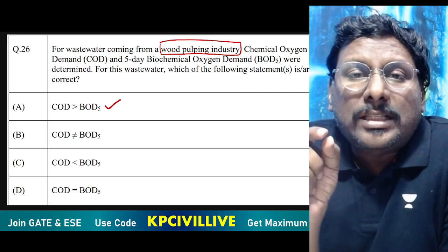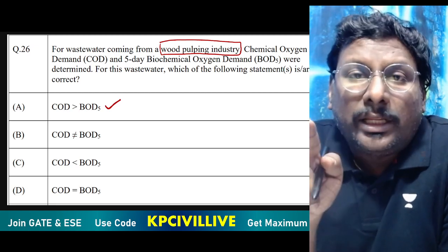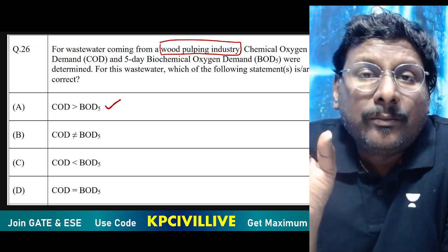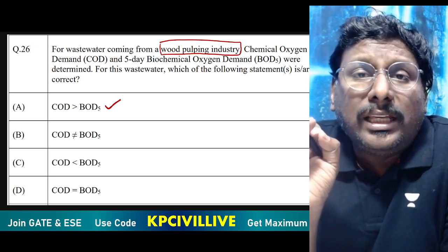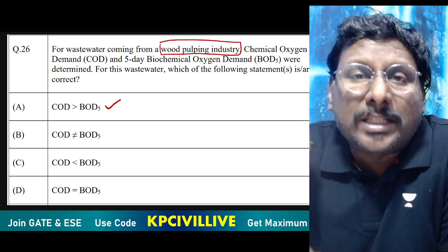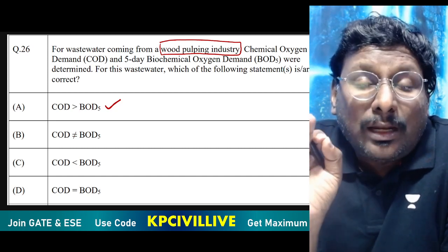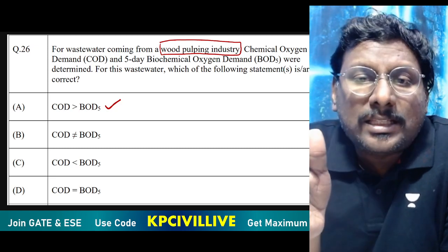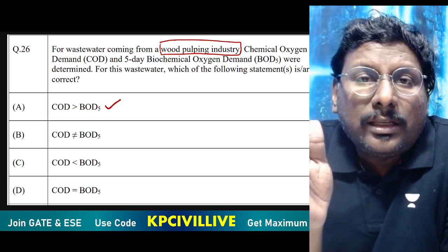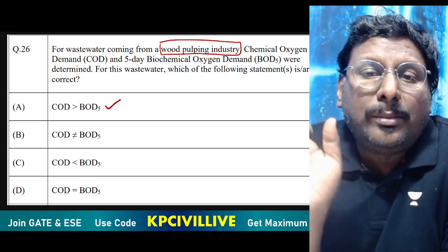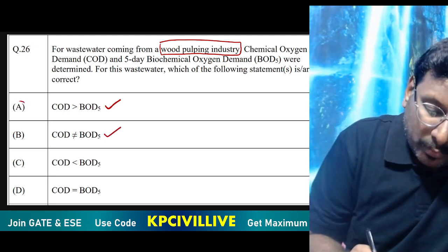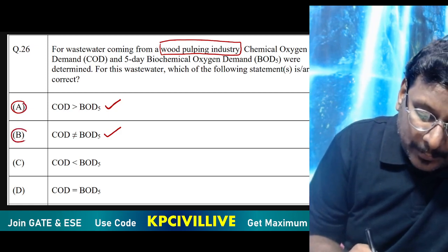And sometimes COD equals BOD, that is ultimate BOD, not 5-day BOD, when biologically inactive organic matter is absent. In such a case, COD equals ultimate BOD, not 5-day BOD. COD is never equal to 5-day BOD. So the answer is options A and B.